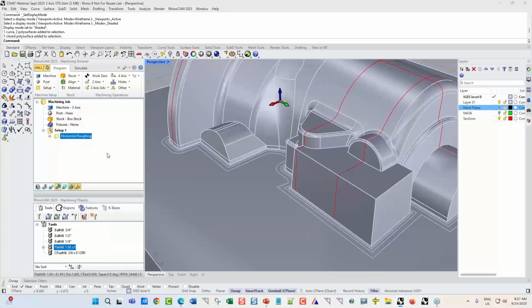That's a good tip there. Also, what you can do is your step overs. Maybe initially you don't need a really tight step over. If you just want to get a good look at what this path is going to look like, you just give it a wider step over, as Joe mentioned, a more lax tolerance, and that'll help speed it up as well. So we got through. Let's look at this.